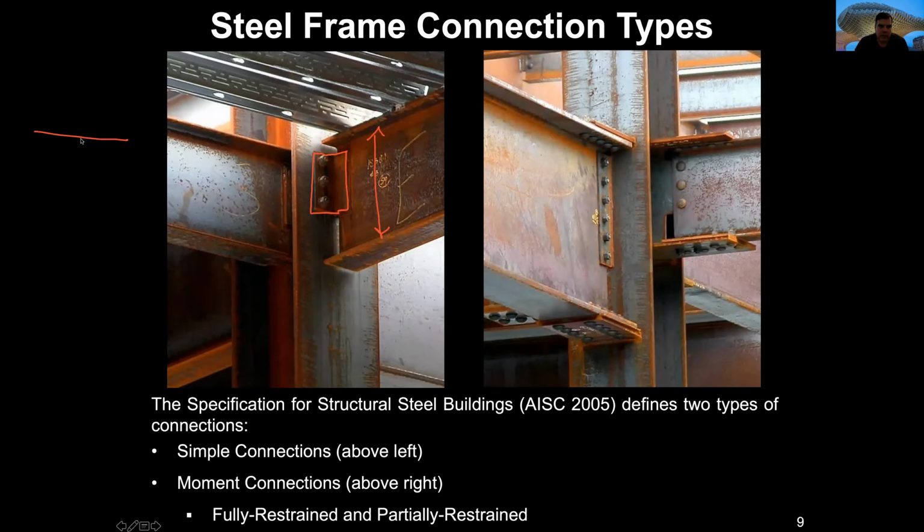Well, an I-beam has three components: you have these elements at the top and at the bottom, and you have the central area. When you have connections only in the central area, the connection is not rigid, because the top part could rotate and the bottom part could also rotate, since it's not attached, it's free at those points.